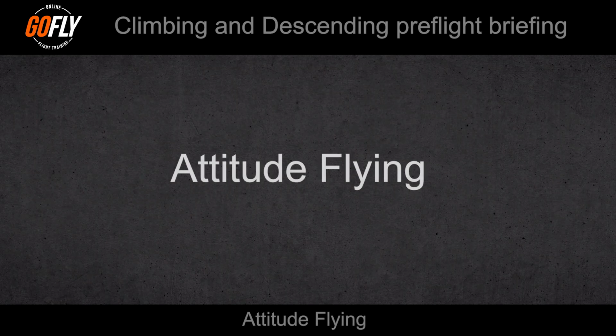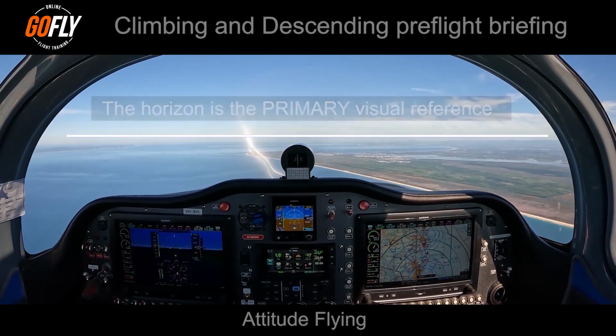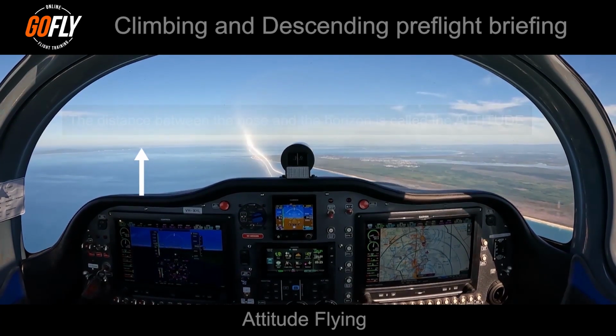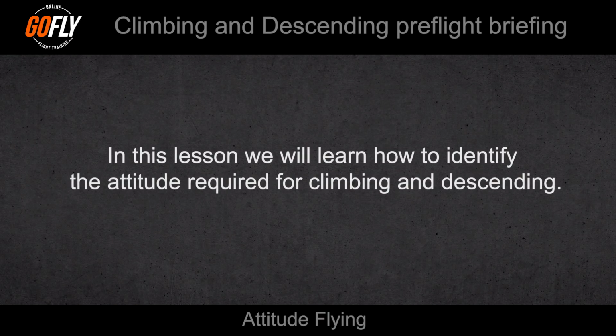As visual pilots, the horizon is our primary reference. We need to have our eyes on the horizon for the majority of the time. The distance between the nose of the aircraft and the horizon we call the attitude. From the last lesson, we learned how to identify the attitude required for level flight. In this lesson, we will learn how to identify the attitude required for climbing and descending.